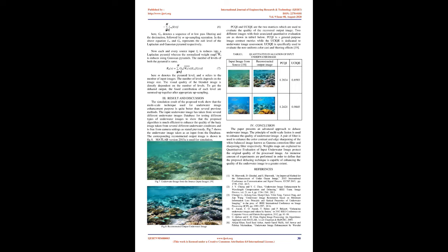The disadvantage of this approach is that it creates a circle of white light or colored light around some of the pixels. This limitation can be reduced by using multiscale linear filter or nonlinear filters. The multiscale reduction of an image is based on Laplacian pyramid. It reduces the image into a sum of bandpass images. The input image is filtered by each level of the pyramid by using a low-pass Gaussian kernel G, and the filtered image is decimated by a factor of 2 in both directions.